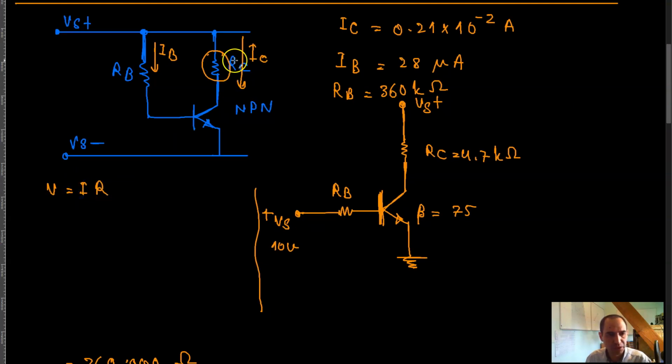Okay. So applying Ohm's law to this resistor, we said that we want the voltage drop across this resistor to be the supply voltage, and we are working with this circuit, right? So this is the load, and the supply voltage is 10 volts. So I set this equal to 10 volts, and for that you need a current, and the resistance of this resistor is 4.7 kilo ohm. Then using this relationship you calculate I of C, equal to this current over here, right? So that tells me that this current has to go through your collector, so that the whole voltage is dropped across the load, and no voltage is dropped here, right?